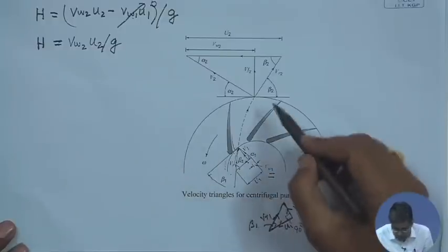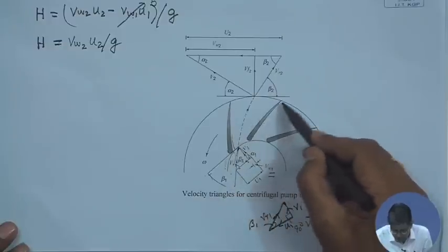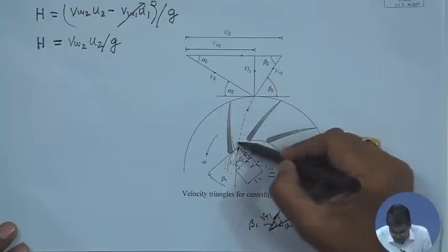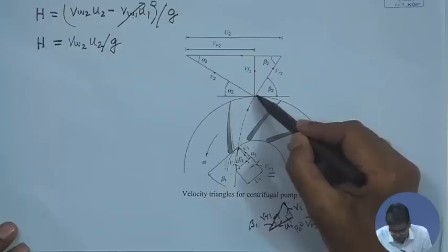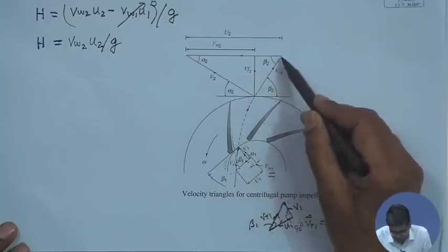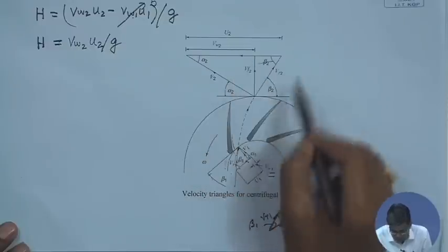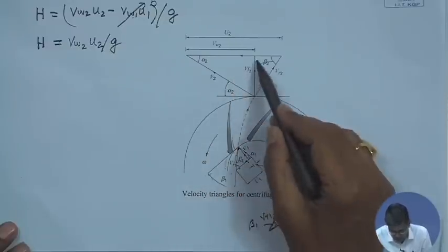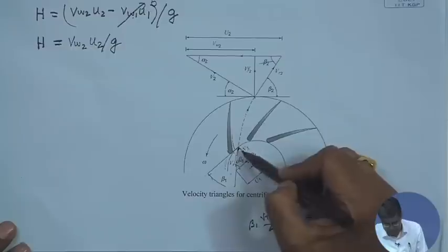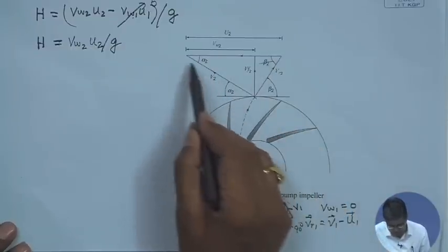Now, you see the outlet velocity triangle. For this typical blade profile, the outlet triangle is like that. This is a representative path shown. This is the blade angle, Vr2 is coinciding with that. This is U2, and this is U1. U2 is much larger than U1. This is because R2 is much larger than R1, the radial location at the outlet. This is U2 and this is V2.